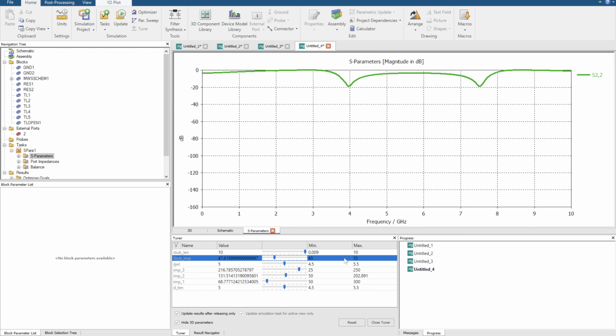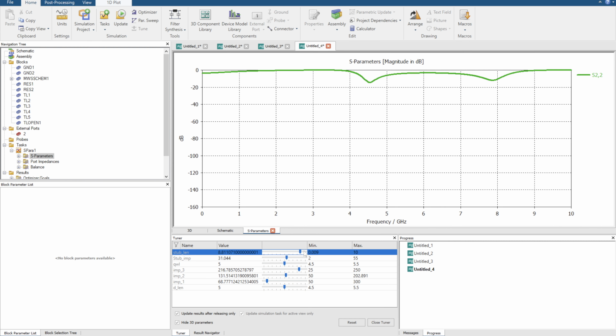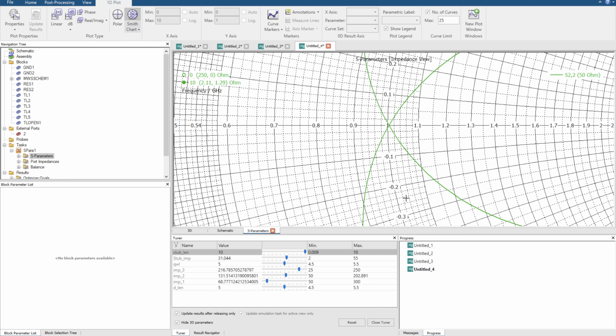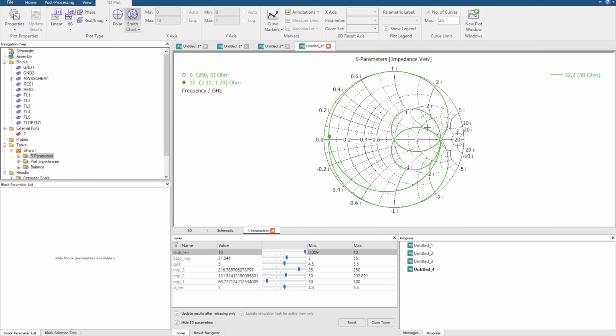Let's drive it to be something low. Let's go all the way down to 2 ohms. So we'll find that, okay, now I've got 2 bands that are perfectly matched, near 4 and one near 7. I can slowly tune that with a length, but you'll find it goes completely out of match when I change the length. So it's a bit tricky when you're working with impedance matching circuits, but we can also tune from the Smith chart. If you can get this swirly nature all packed in very close to 1, then you're actually going to have a very wideband impedance matching network.